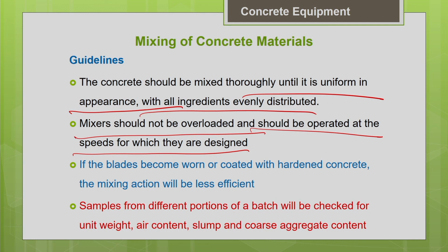And you should clean the concrete mixers immediately, because if your blades are going to get coated with the hardened concrete, it is going to affect your mixing action. In many job sites you can see blades with hardened concrete, because the concrete mixers are not properly maintained, not properly cleaned after every mixing process. So, you can see that the concrete might have hardened. So, that will also affect the mixing efficiency.